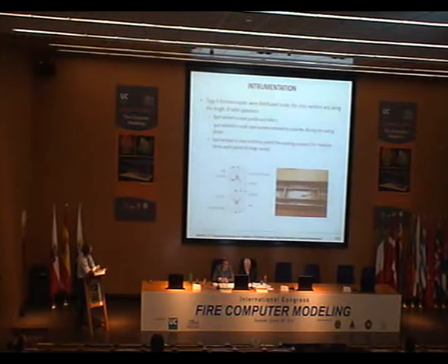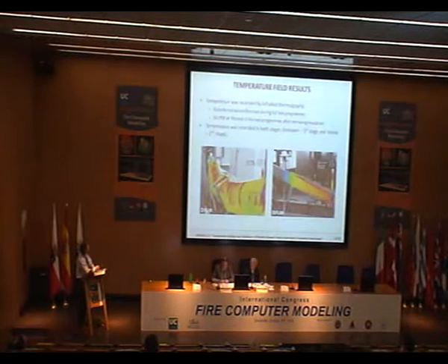Let's talk about instrumentation. We decided to use some thermocouples. Some of them were spot welded to the steel profile, and the others were welded to a small steel washer encased in concrete, as you can see in the picture on the right. Of course, we also used some spot welded to the steel profile to control the heating process of the beam. Now I can show you some pictures.